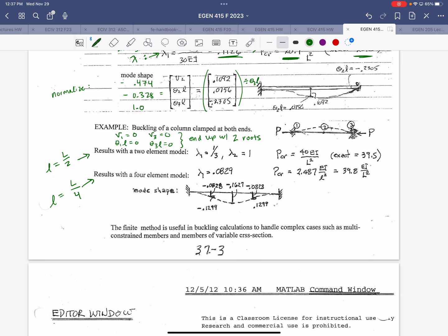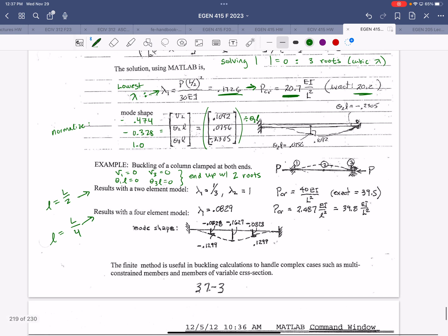So with like the simply supported beam we had earlier, and we had 4 roots, what would those other 2 roots be, and like how do we, I mean, I guess we know which one controls it's the lowest, but are those of any value to us? Yeah, so they would represent the higher buckled modes, if that's what you're interested in. Yeah, there would be an inflection in there, yeah. Okay. Usually we only care about the first buckling mode, right. But yeah, that's what those would represent.